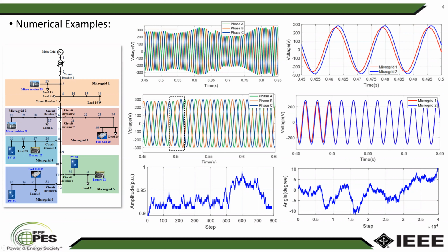From the simulation result, you can see that after we interconnect the system, we couldn't maintain stable operations. The reason is given in figure 2: before we close the circuit breaker, there is too much difference between their voltages. The third and fourth figures show the result when we use the reinforcement learning technique. We also close circuit breakers 1 and 2 at 0.5 seconds. From this result, you can see that by using the reinforcement learning enabled control system, we can quickly adjust the output voltage so that we meet the interconnection requirement.